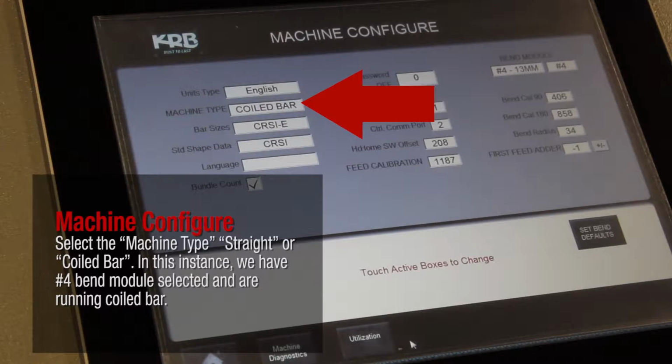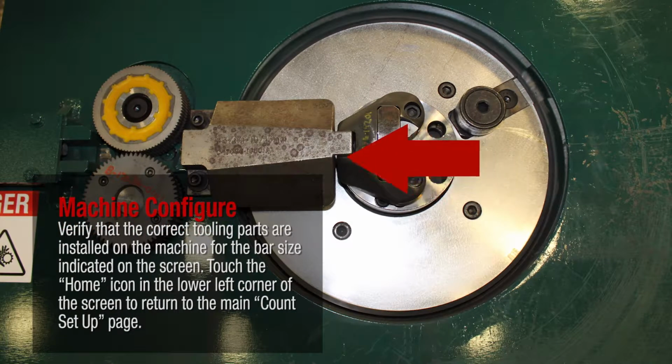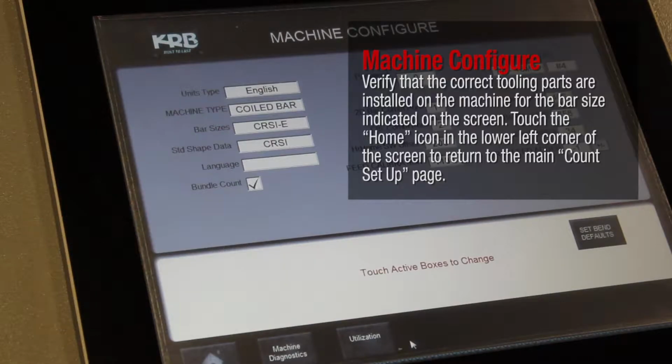Select the machine type, straight or coiled bar. In this instance, we have number 4 bend module selected and are running coiled bar. Verify that the correct tooling parts are installed on the machine for the bar size indicated on the screen. Touch the Home icon in the lower left corner of the screen to return to the main Count Setup page.